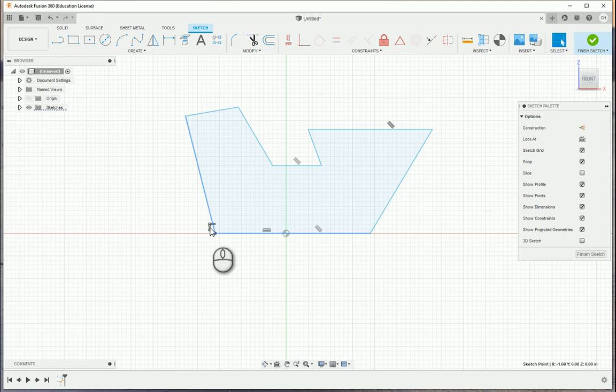So coincident constraint means the endpoint of one line and the endpoint of a second line are meeting to make a corner, an edge, or some sort of placement. So a meeting conjuncture means those 2 points are coincident to each other. They're right on top of each other. They're constrained to each other in space. So as we take a look, same kind of thing here.